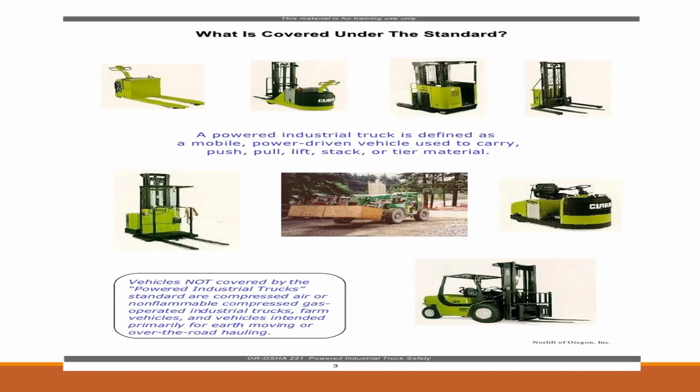So whenever we have lifting activities and transportation going on in the open area, then we can recommend the diesel operated. But indoors, for example in an air conditioned operations area, or where the smoke is going to stay within the facility, diesel operated is not allowed. Especially in food and pharmaceutical companies, even in their warehousing, diesel operated forklifts are not allowed. We have seen this in one of our clients' warehouses.